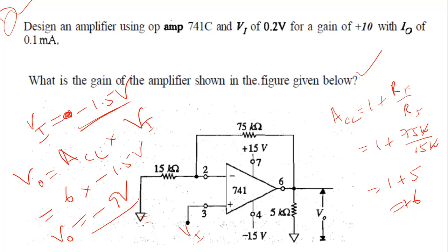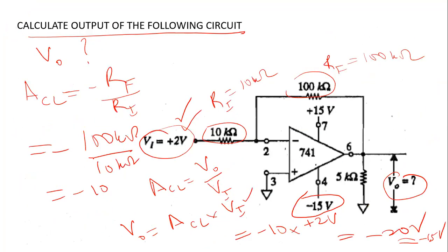So that's how this kind of op-amp amplifier works. It amplifies without altering the sign in the non-inverting configuration. And in the inverting amplifier, even though it amplifies depending on the gain you choose, it flips the voltage. Positive voltage flips to negative voltage and vice versa.